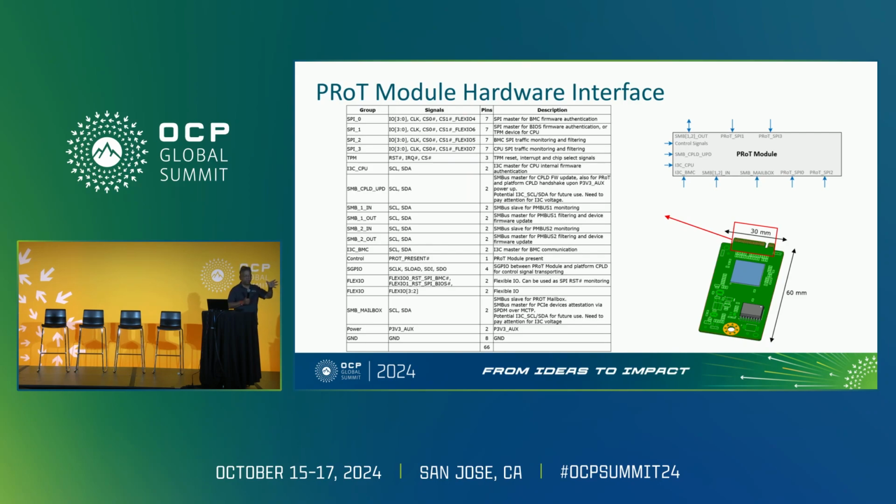I'm going to propose this to OCP as well to make it a standard, but these are the key things here, how we are defining the pins. The main thing is that we're not defining something new. We're staying within M.2 form factors. And the M.2 pin definition is very standard. The storage guys, server guys, compute guys, edge guys, everybody is using M.2 today. So this fits very nicely. M.2 has 67 pins. We need 66 pins, so it fits properly.